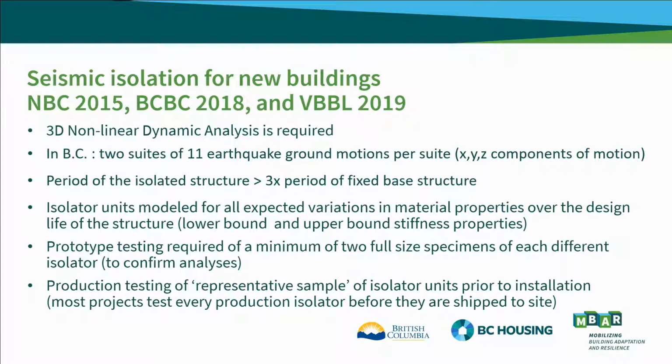Prototype testing is required for 2 full-size specimens to make sure that what is modeled is reflective of the actual devices. And then every isolator that is produced and sent to the site usually is tested, but the code right now only requires representative samples. But most projects just test every production isolator before it's shipped to the site for tremendous quality control of the performance.